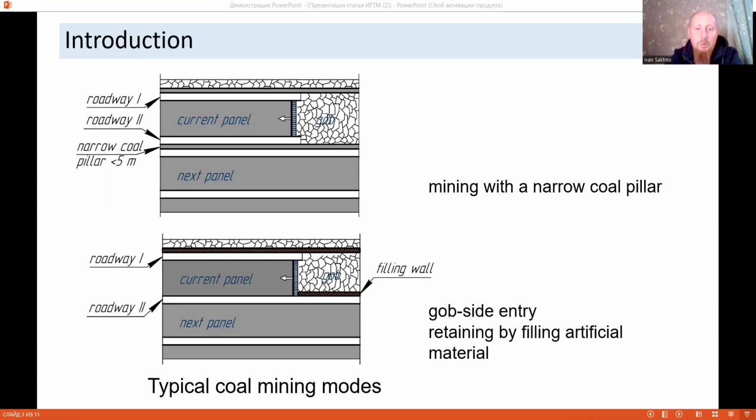In recent years, the use of gangue was proposed as a fill-in wall material that can help remove gangue from the ground. This reduced the cost of the fill-in wall and solved the problem of rock waste. Coal gangue concrete is a concrete material utilizing gangue as a coarse aggregate and cement as a cementing material mixed with a certain amount of additives. In this paper, based on a geological condition typical for the Ukrainian Donbass, two variants of fill-in wall, high-support cemented fill-in and gangue concrete wall, were researched.